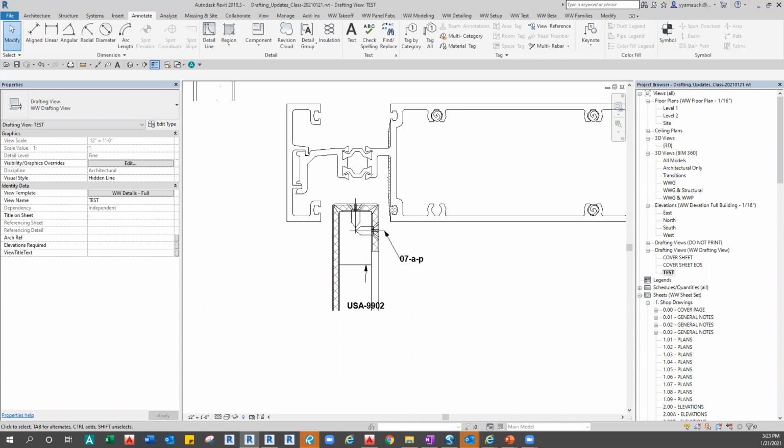Okay. I think they were manually being adjusted in the unit assembly drawing for these non-rectangular glass. Yes, because the non-rectangular glass right now is not a curtain panel, it's a system panel and it only goes daylight. But we're having a meeting tomorrow to figure out how we're doing the non-rectangular lights in G units. So hopefully we'll have a solution as we come out of that meeting. Okay.